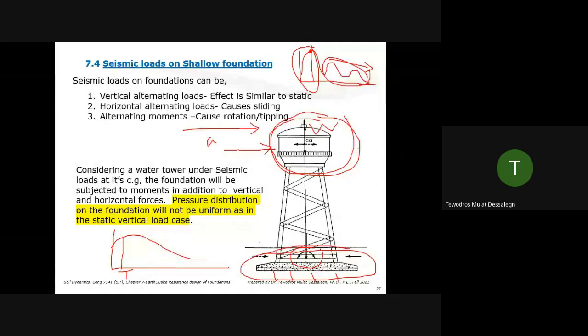Otherwise, the more realistic approach is to model the whole thing. Anyway, you're modeling it to estimate the period, right? So run that using the full response spectrum or a time history. If you do that, your forces at the bottom will be less, but you have more tasks to do. Modeling and simulation may take a week or more, depending on the complexity of your structure. So any structure you can have.